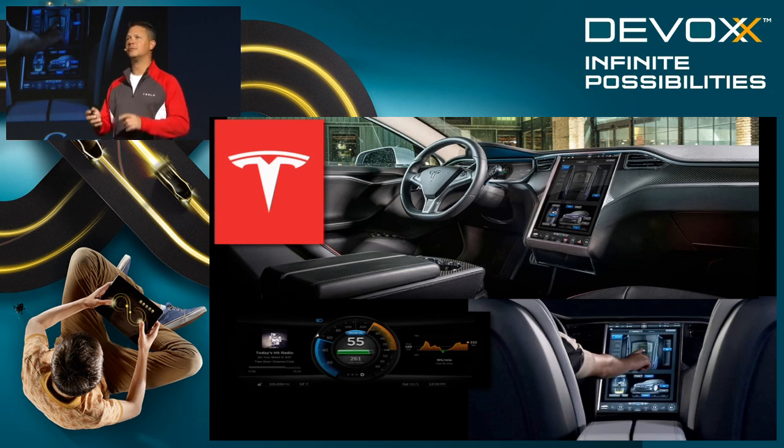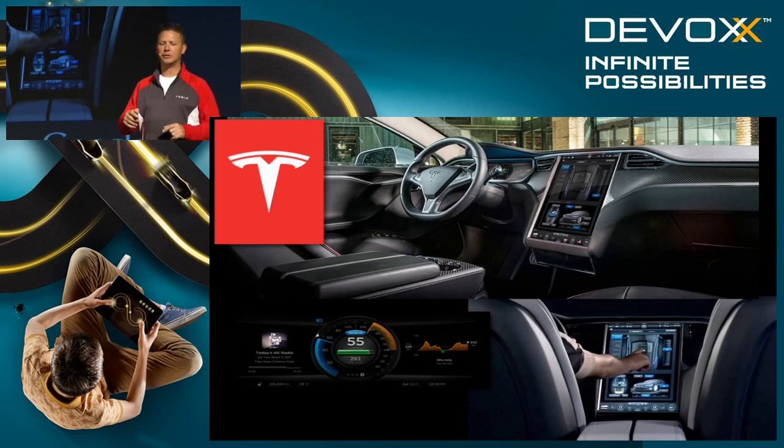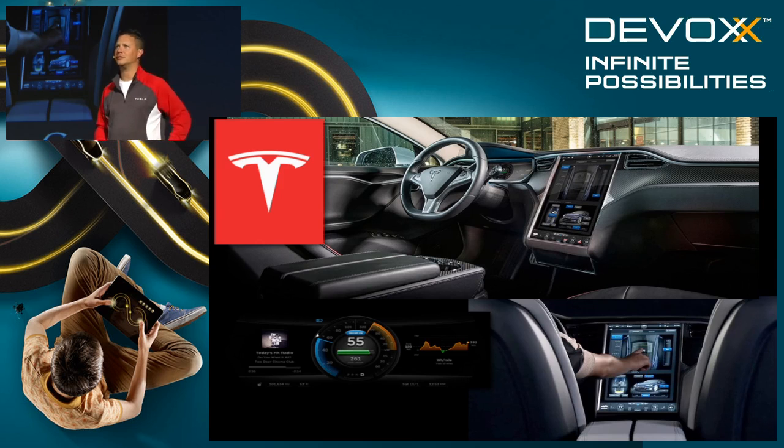The instrument cluster is actually running an Nvidia Tegra 2, which is a lesser processor, but it has less screen real estate to deal with. And the biggest processor hog in terms of memory is the navigation system, which we actually had running on the Tegra 2, with a whole bunch of network communication between the 2 systems, with Google Map tiles showing on the bottom right that were just showing GPS waypoints generated by the navigation C++ code on the top. So it's a very, very complicated and very custom built system.